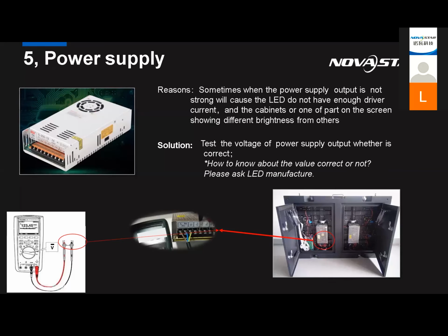The fifth reason, power supply. I know some cabinets use one power supply for the LED panel and the receiving card at the same time. But sometimes the power supply between each panel is different. So this would be a reason.